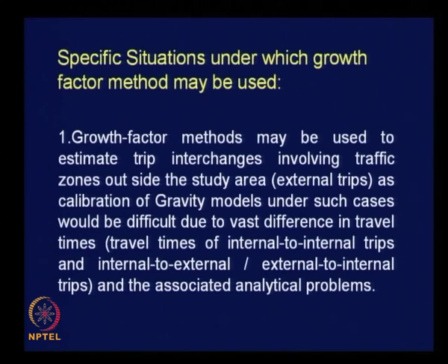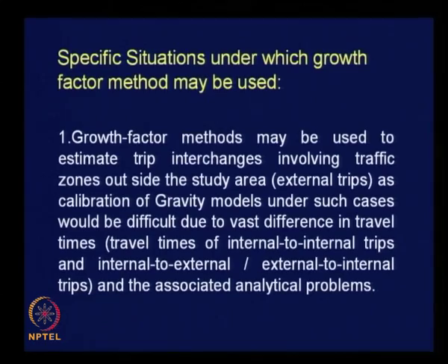Within urban area, your travel time range could be nearly a minute to, let us say, about 70 minutes. Whereas if you take a travel time between Chennai and Vijayawada, Chennai and New Delhi, it is not going to be comparable. When such vast variation is there, you cannot apply your gravity model, it will not work, okay.